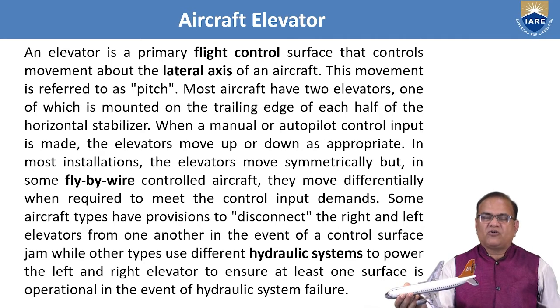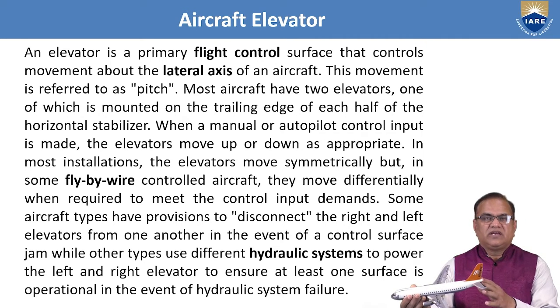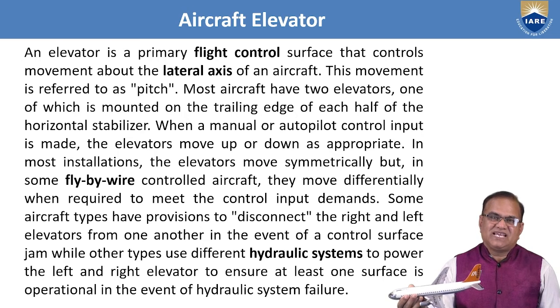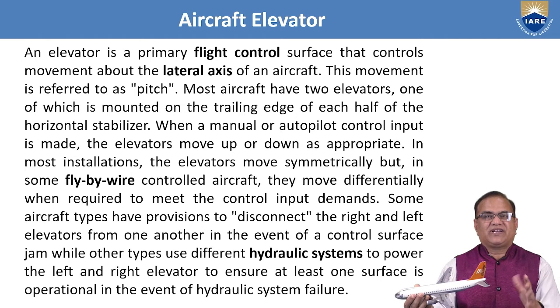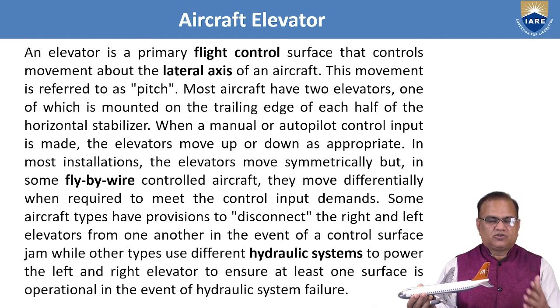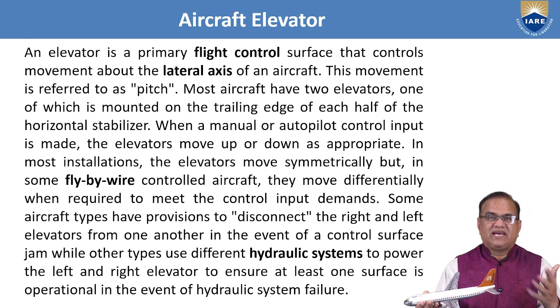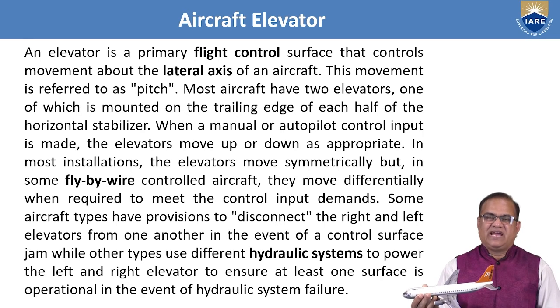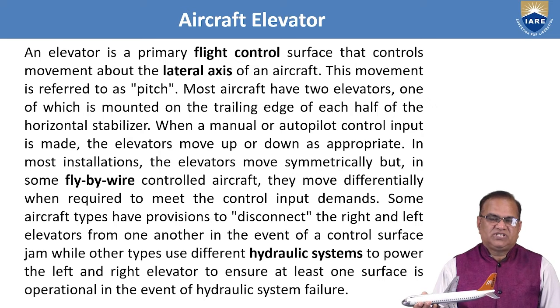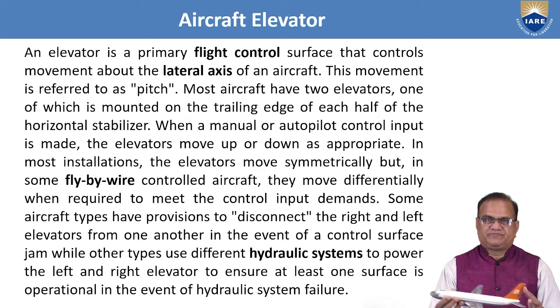In case of hydraulic system failure, it is always essential that at least one elevator should be serviceable, so that if one side is jammed, the other side can function and some part of the required pitching motion can be achieved.